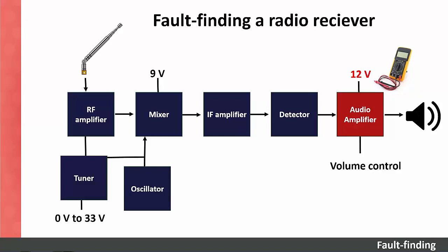Notice how the focus has now shifted to another area of the receiver, the power supply. If the voltage is present, but lower than 12 volts, then one or more of the components, normally transistors or an integrated circuit in the amplifier stage, is faulty. A faulty component always tends to draw more current, thereby reducing the voltage due to Ohm's law. This is one of the best clues that one could hope for. The faulty component should be removed and tested for correct functioning and replaced when necessary.